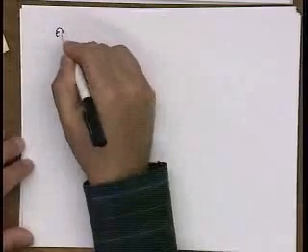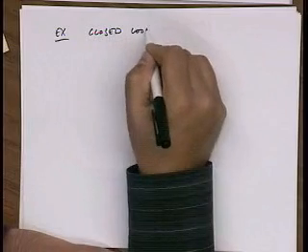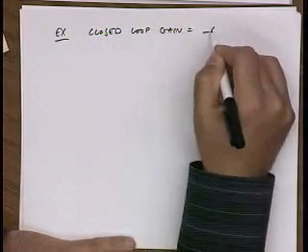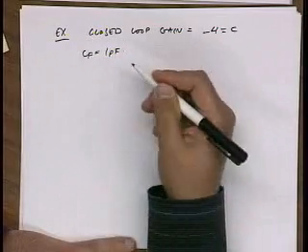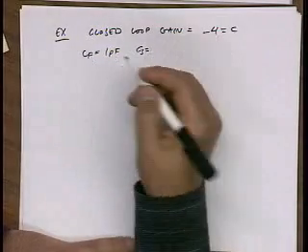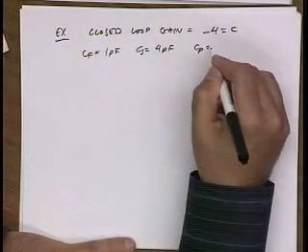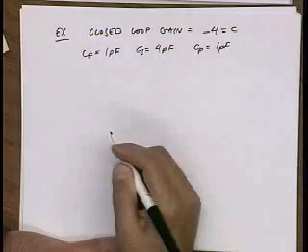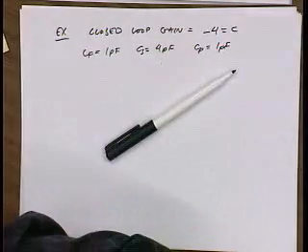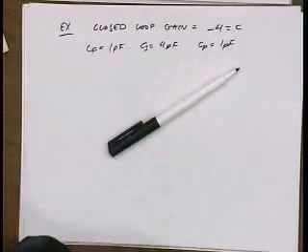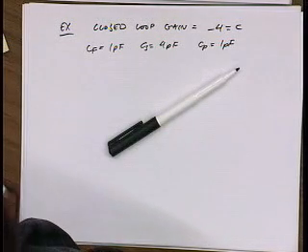Let's say I want to design an amplifier with a closed loop gain of -4, and in this particular problem, I use a 1 picofarad feedback capacitor, 4 picofarad sampling capacitor, and I end up with 1 picofarad of CGS capacitance. How do I size these capacitors, incidentally?